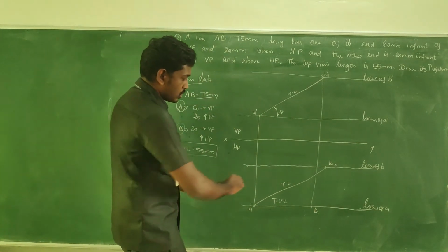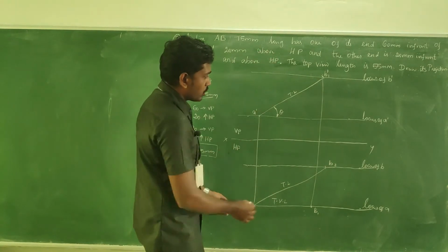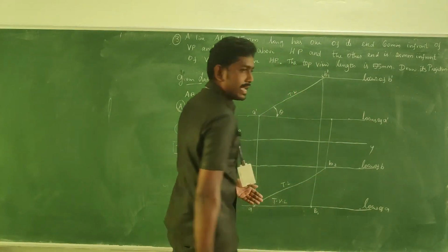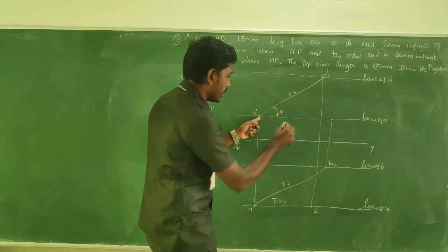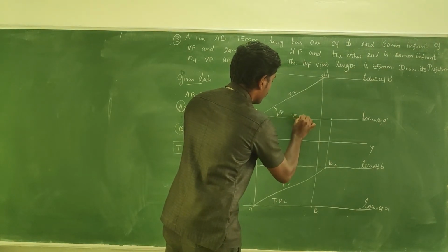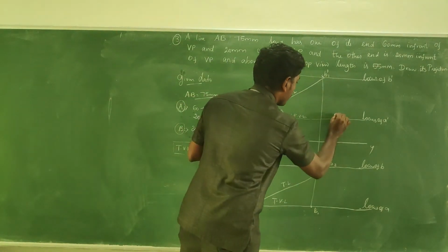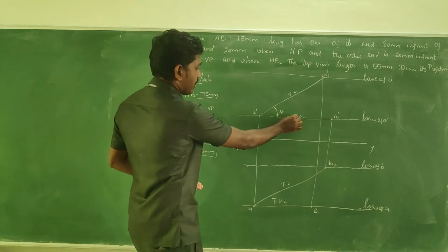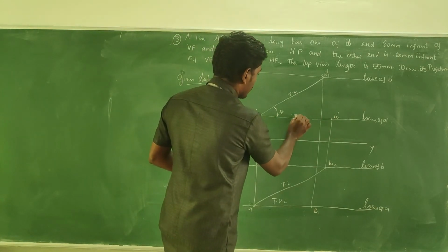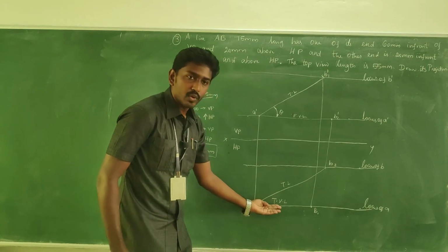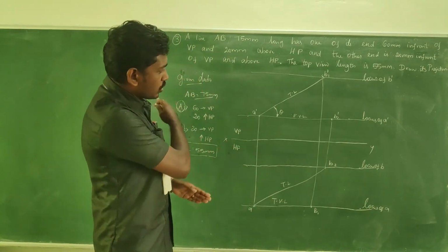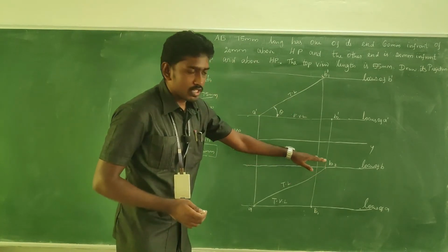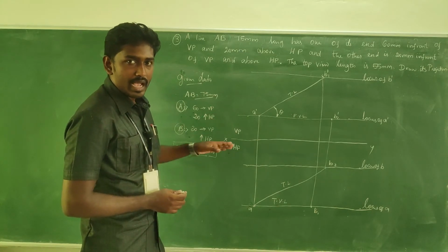Now it is easy. True inclination is there. If you draw the projector extension line from B2 and intersect with the locus of A dash, you get the front view length. This point becomes B2 dash. Now see, all the data are available. Front view length is there and top view length is there, right? So now just go and change the position of those lines to the locus of B dash and the locus of B. You can obtain the final front view and final top view.